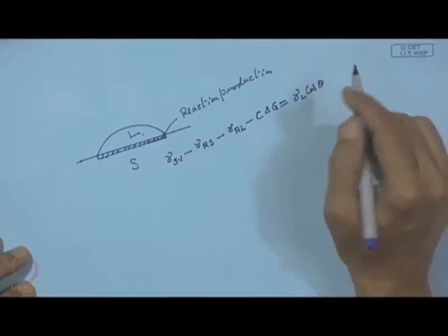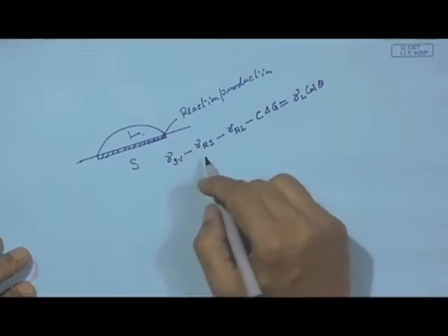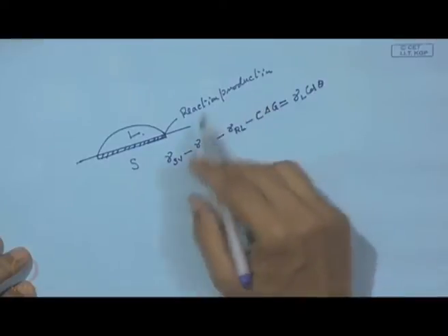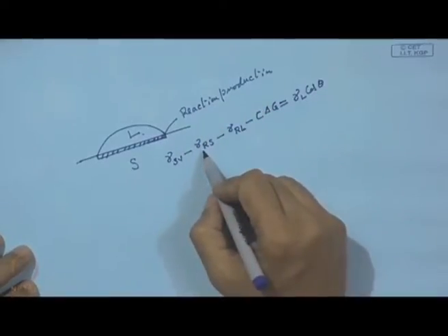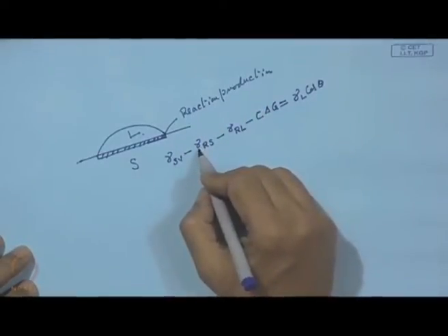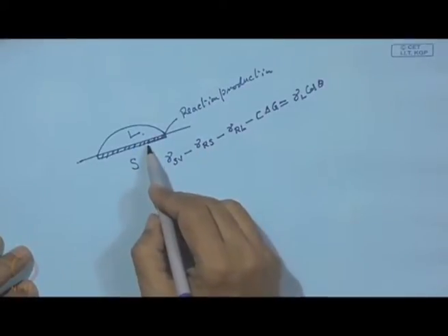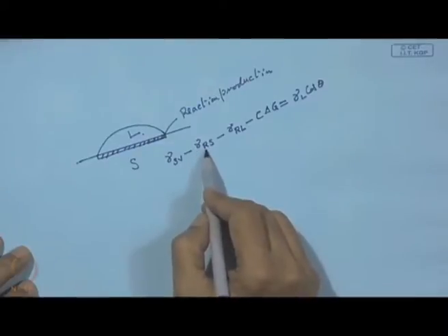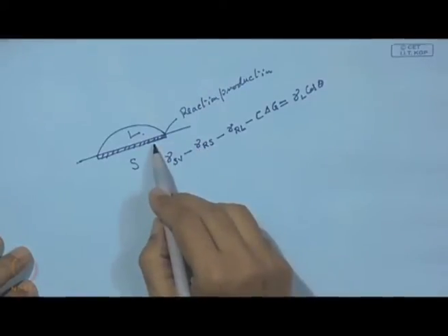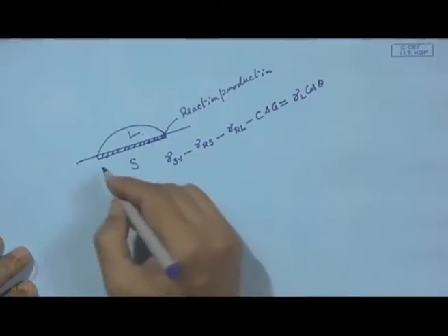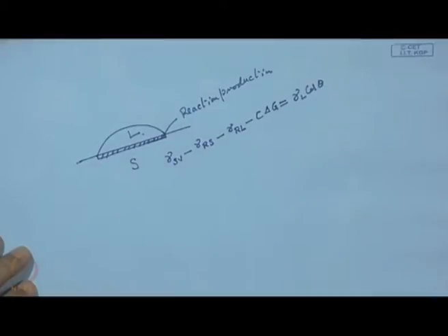So, this is just the modification with respect to the non-reactive wetting case. Here, gamma RS is actually the interfacial energy between this reaction layer and the solid. So, R stands for the reaction layer and gamma RS is the interfacial energy in this boundary.